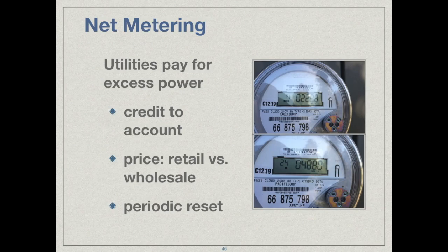If you're getting a credit, then you're probably getting the retail value of the electricity. In other cases, you may be simply paid on a monthly basis for the excess energy, and sometimes that's not the retail value. So in any case, you need to look at the net metering policy that's going to govern the site where you're building and factor that into the economics of your decision.